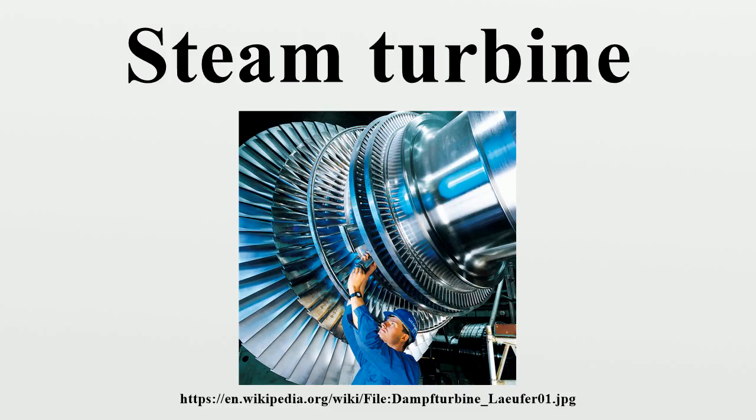A number of other variations of turbines have been developed that work effectively with steam. The de Laval turbine accelerated the steam to full speed before running it against a turbine blade. De Laval's impulse turbine is simpler, less expensive and does not need to be pressure-proof. It can operate with any pressure of steam, but is considerably less efficient.